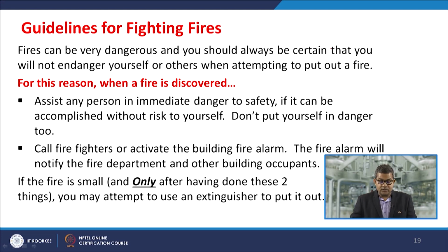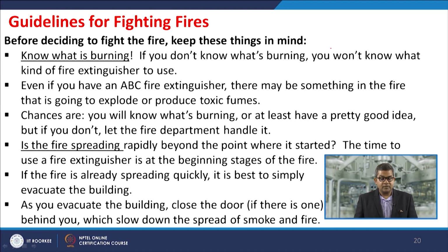Call the firefighters or activate the building fire alarm. The fire alarm will notify the fire department and other building occupants. If the fire is small, and only after having done these two things, you may attempt to use an extinguisher, the appropriate extinguisher, repeat, the appropriate extinguisher, to put it out.